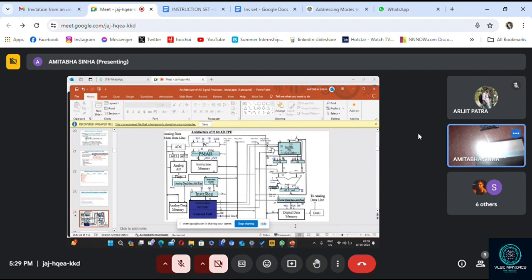So these are the three leads of the operational amplifier. I'm not considering the power supply and all. Let's say in the forward path there is a resistance R1, and in the feedback path there is a resistance R2, and output is V0. Input is V in. So V0 will be equal to minus R2 by R1 into V in.